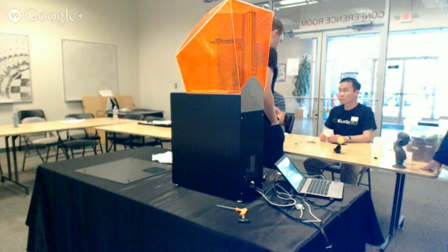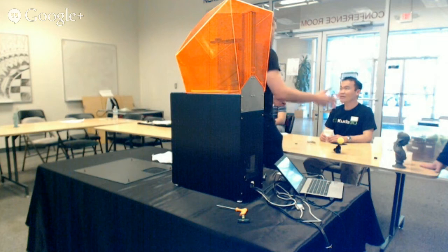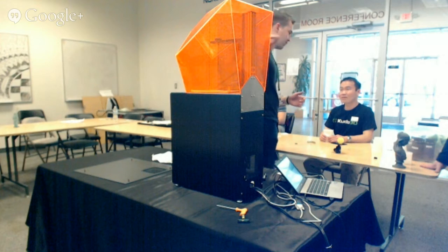It's very impressive if you were able to do that, because the part has a very small surface area per layer, just a couple of dots. Your supports are very flexible. A lot of people, when they start out, essentially raise the build platform, bring the resin back down, so that it's surviving that. But if you don't do that, when you hit print, you'll have interlayer separation problems.